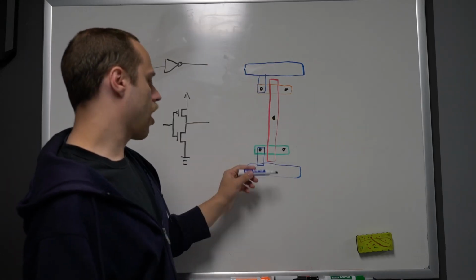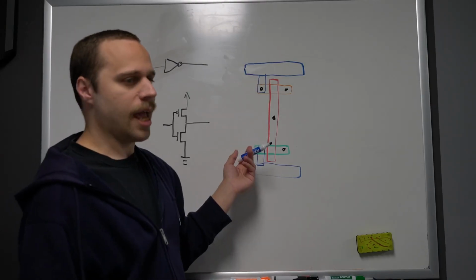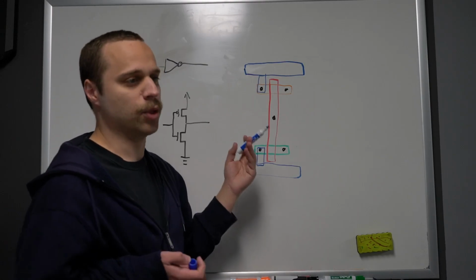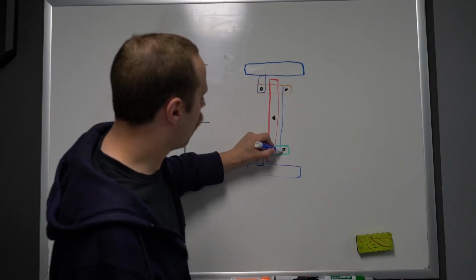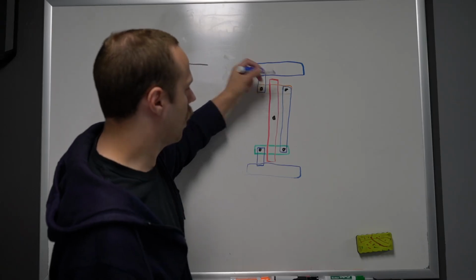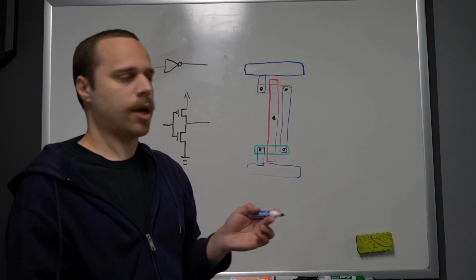The one below here is going to have the NFETs at the top and the PFETs at the bottom. And so this is kind of the canonical orientation with power at the top, just because that's how people normally think of it. Anyway, now we can go add our output terminal here, and we're only looking at metal 1. We don't care about the upper layers. Those are typically just used for cell-to-cell interconnect, not within a cell.